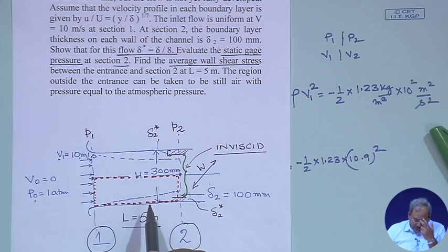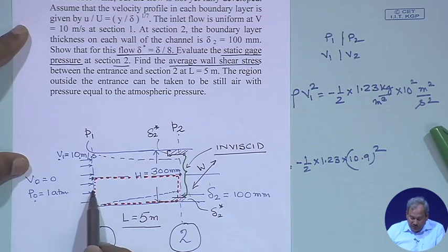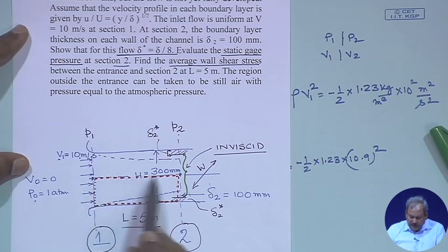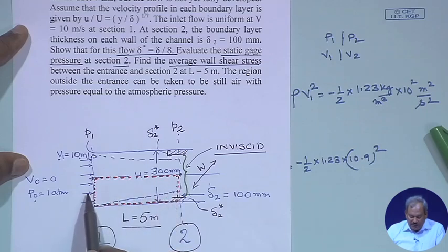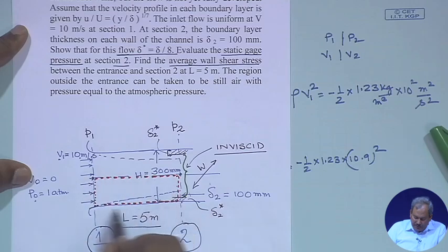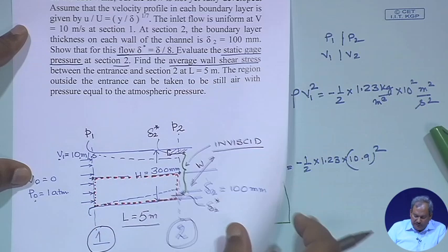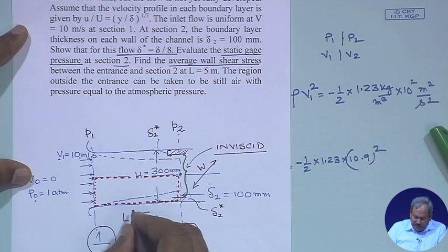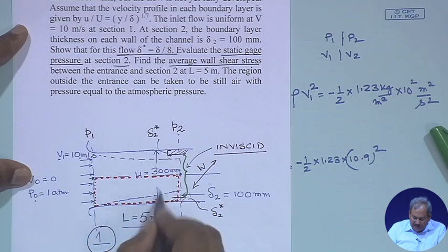So, the two surface forces acting are due to pressure difference and due to shear. Since the duct is horizontal, there is no body force, and you have convective transport of momentum out of the system. Now I am going to write the momentum integral equation for this half of the duct and find the wall shear stress, tau, exerted over here.